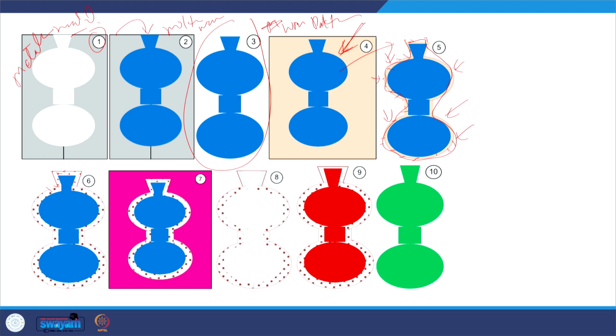So this is the step where the ceramic powder particles will be sprinkled so that they form a kind of shell. Now this process will be repeated until we get the wall of the desired thickness. Slurry coating, like dipping the pattern into the slurry, then sprinkling the refractory powder particles over the slurry to realize the coating, the shell of the desired thickness.